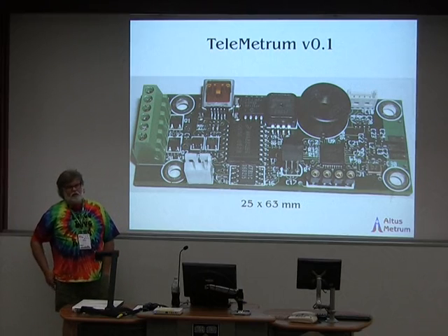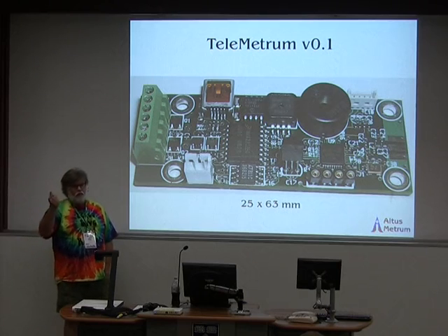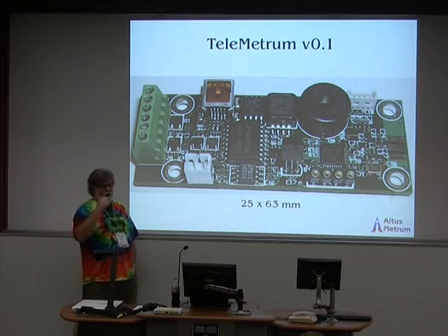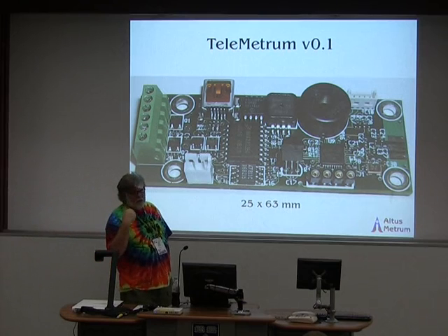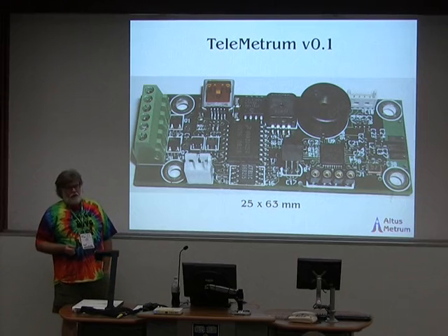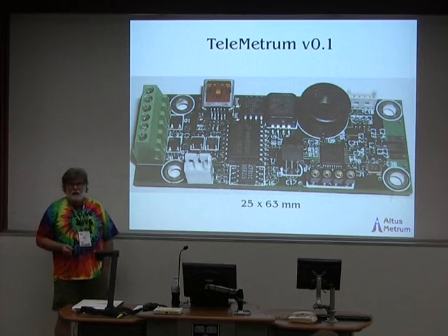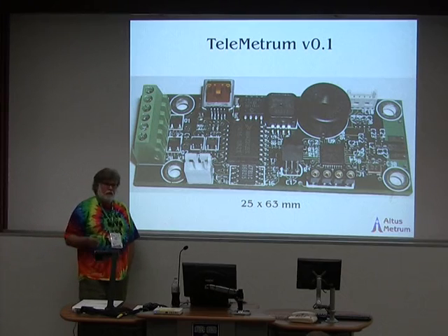Yeah, so if you're using a handheld 5-element Yagi on the ground and a quarter wave whip in the airframe, and things are oriented right and you're in free space, i.e., approximated by atmosphere, with clear line of sight and without a lot of multipath reflections from the ground, you ought to get something like 30 kilometers range. That's with 10 milliwatts, okay? That's an error-free data stream at that range.